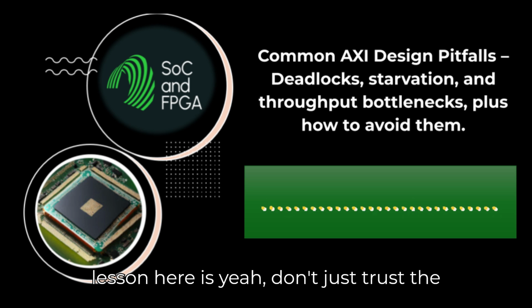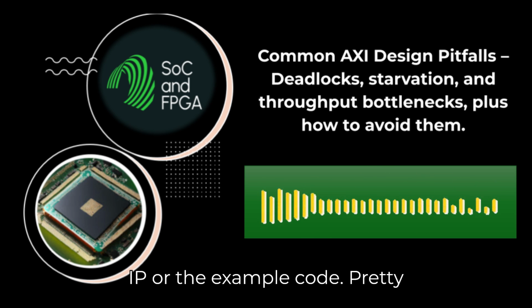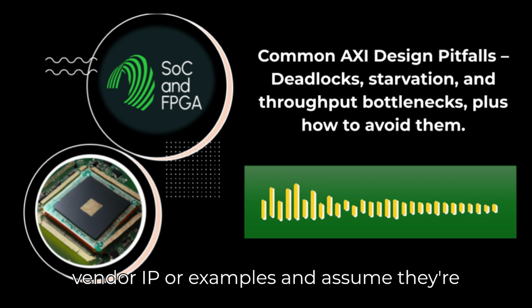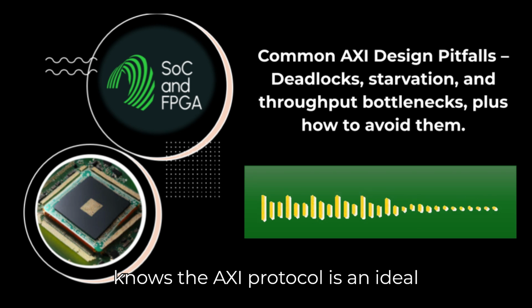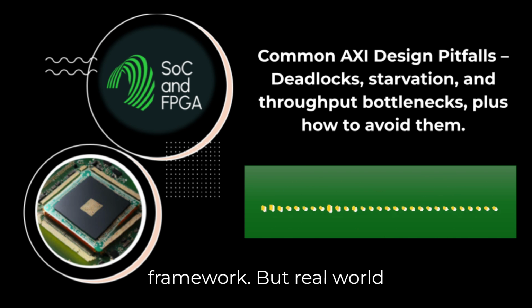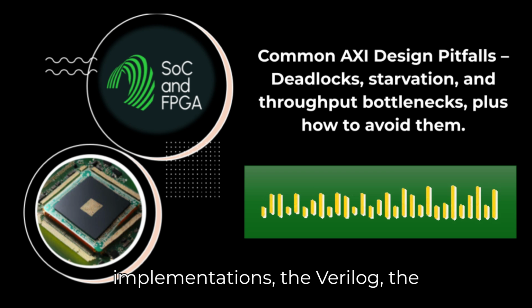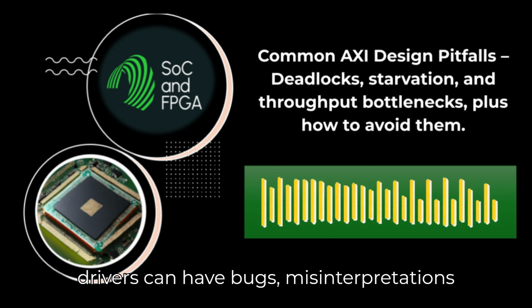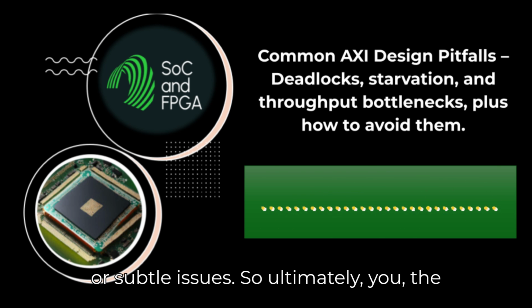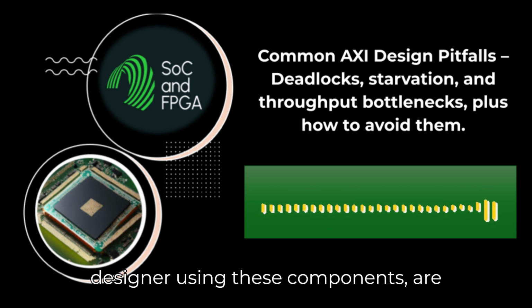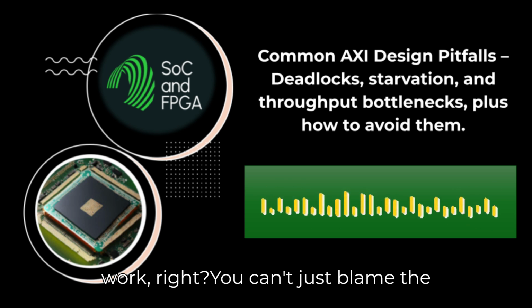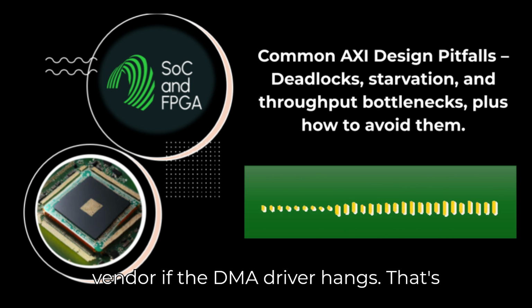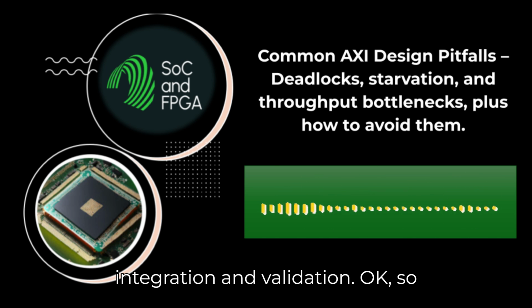Okay, so the lesson here is, don't just trust the IP or the example code. Pretty much. A newer designer might look at vendor IP or examples and assume they're perfect. But an experienced designer knows the AXI protocol is an ideal framework, but real-world implementations, the Verilog, the drivers, can have bugs, misinterpretations, or subtle issues. So ultimately you, the designer, using these components, are responsible for making the whole system work, right? You can't just blame the vendor if the DMA driver hangs. That's the reality. You own the final system integration and validation.